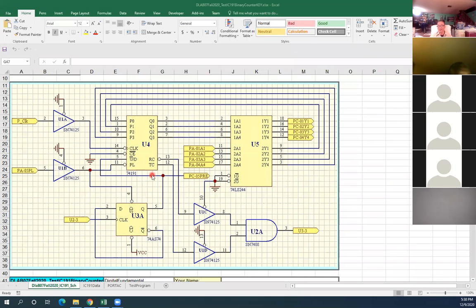One gets 8 bits, one gets only 1 bit at a time, depending on the application. In this case, I need only 2 inputs, for the clock pin and the parallel load pin, which need the buffer. So I need to use a 74125. And the other one gets 8 bits, so that's why I need to use a 74244. Just the buffer. Okay?